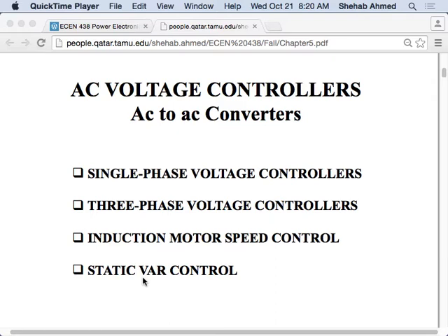So it's something you don't want because they will cause harmonics. These harmonics can interact and ruin your other equipment, or can ruin your voltage profile. If you ruin your voltage profile, maybe your protection system will trip, and maybe these high spikes in current will be detected by your protection system. It will trip because you have very sensitive loads that you've set your protection system to protect. There are other reasons to avoid this too.